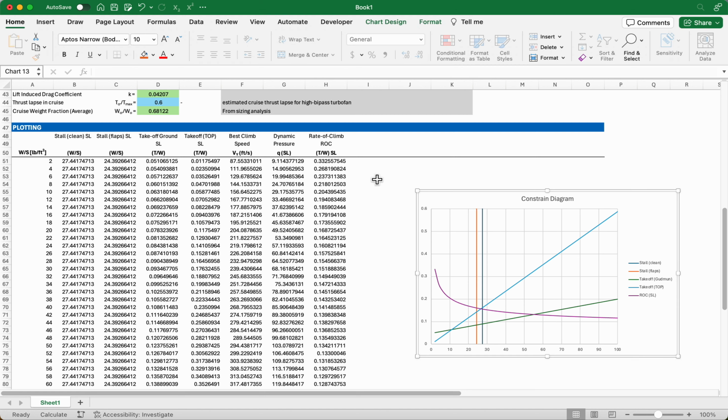So I'm going to change, as we increase our altitude, density, the air is thinner, our rate of climb is going to decrease. Eventually the air is too thin, you can't climb anymore, and we reach our absolute service ceiling. So you can add a service ceiling requirement, which basically sets my rate of climb to 0. Or if you want your service ceiling, that's by definition when your rate of climb reduces to 100 feet per minute or less.